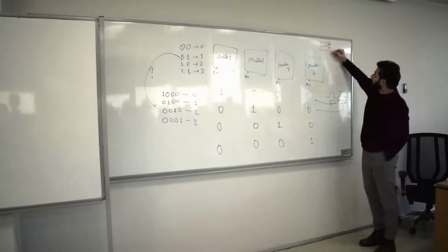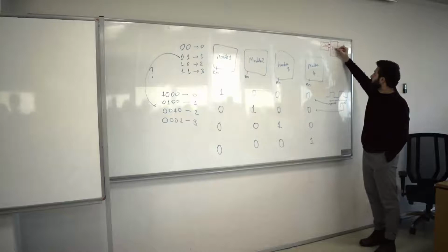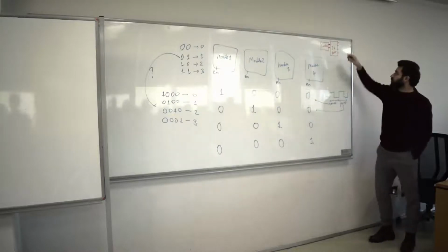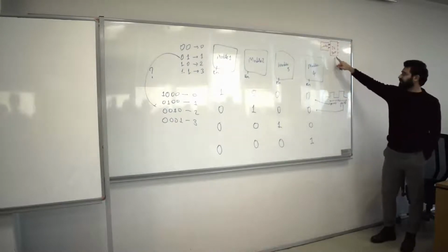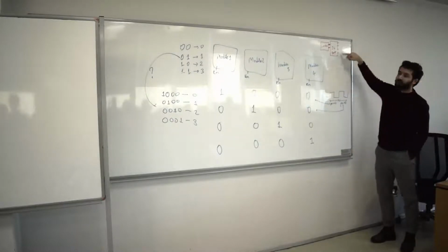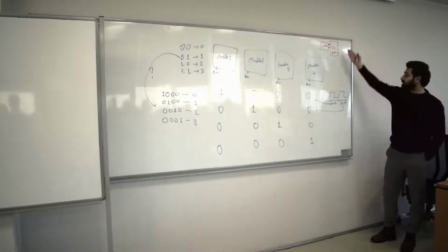So now you connect that to a decoder, because if you have 2 inputs, you get 4 outputs in the decoder. So this is a 2x4 decoder, right? It decodes those 2 bits to minterms. And we know that if this is a decoder, only one of the outputs could be 1, the rest of them should be 0, because these are minterms.